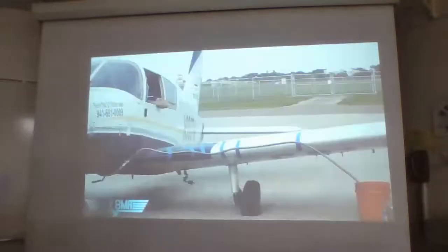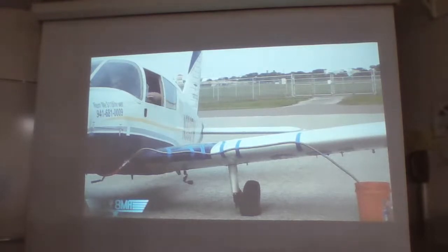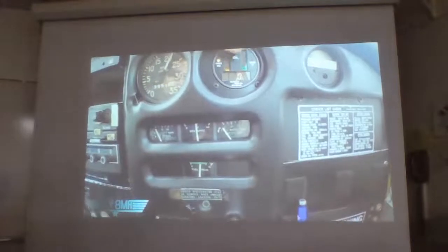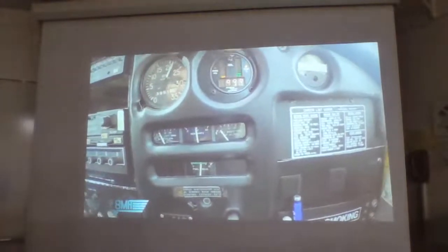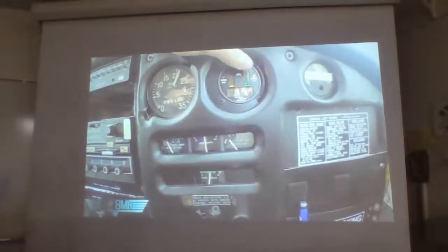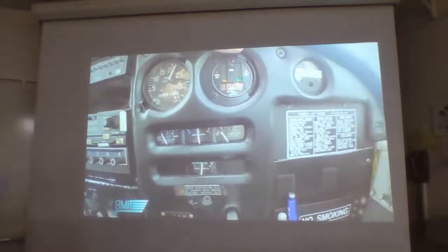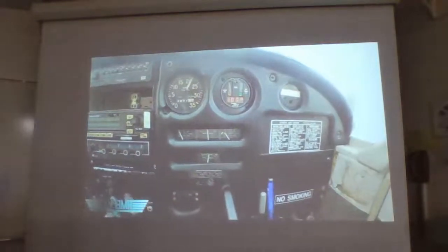That's all right. So we can see just the tiniest bits, little gulps of oil being shot out of there. The last little bit's oil, but obviously 0 pounds of pressure here, 0 psi. No oil pressure. Oil temp has fallen pretty low here. 99, it's not really reading that accurately, obviously. Oil temperature is rising, though. Oil pressure is 0. Oil temperature is coming up.